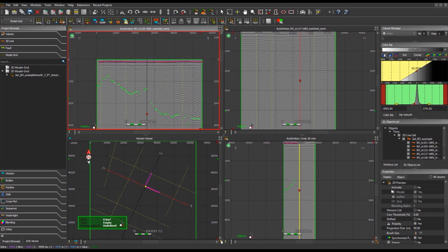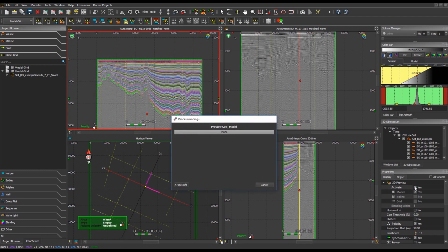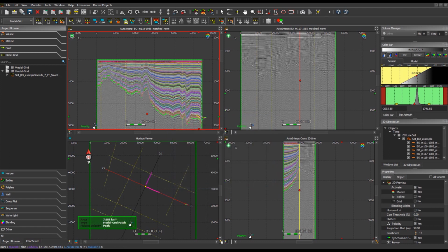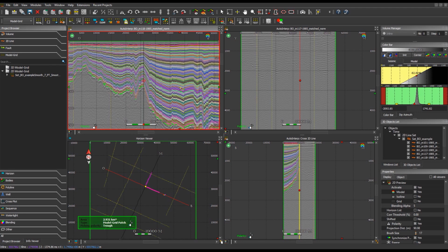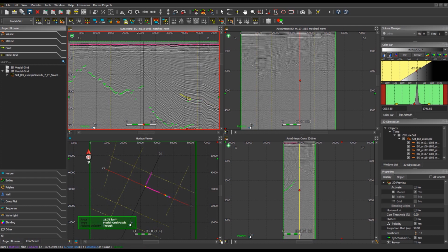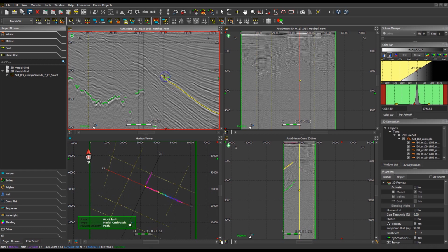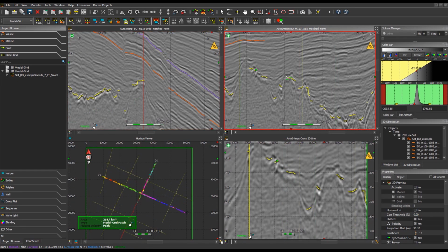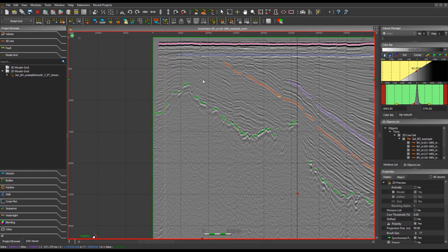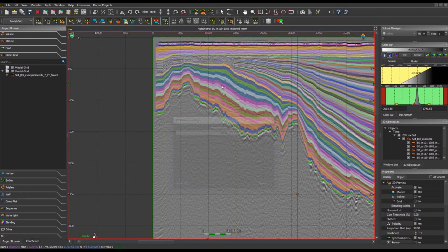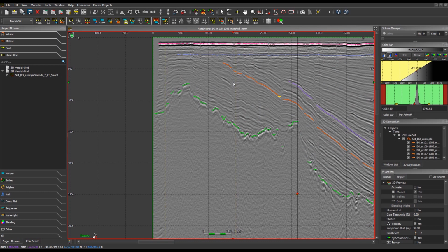The preview of the 2D geomodel can be activated from the Properties panel Display tab by ticking the Activate and Model options. Alternatively, press T to activate or deactivate the model preview. During the interpretation of a horizon, it may happen that two parts of the same horizon are overlapping. Each time this conflict occurs, click Apply to validate the modification or Cancel to cancel the modifications. For each 2D line, the more interpreted horizons, the more refined the preview model.